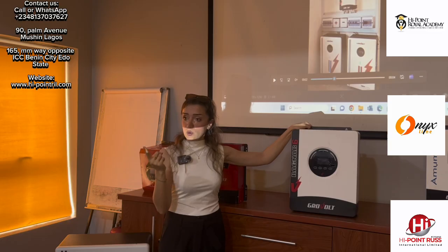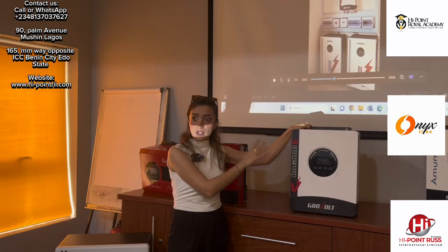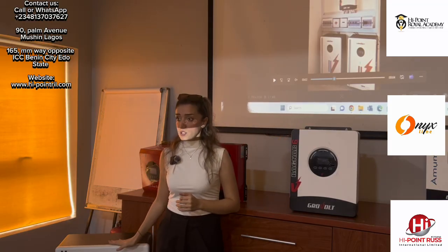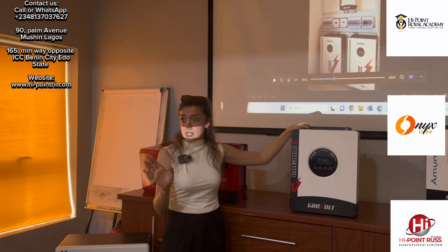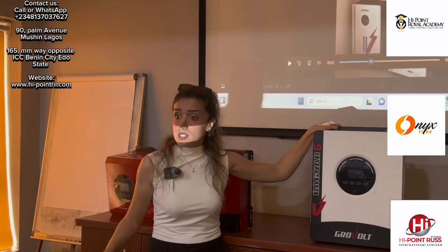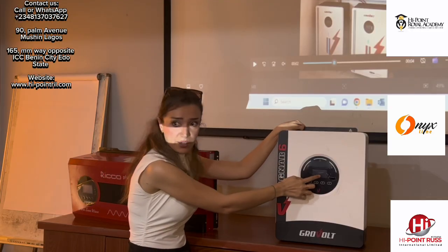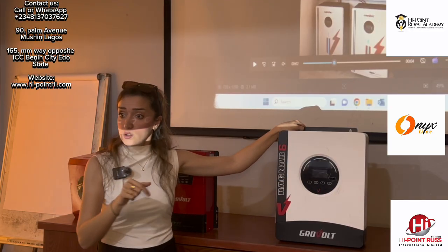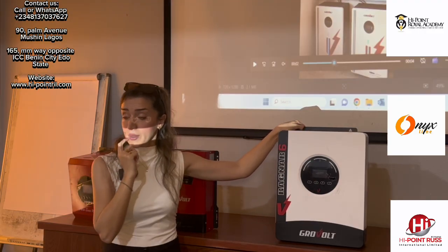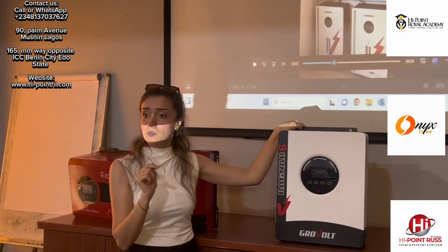If you choose 0, that means it's the default BMS. If the inverter is not communicating or doesn't know about this BMS protocol, put it easily at 0, default BMS. So it will read this lithium battery, but without communication blinking here. If you put 1, you will see the blinking here, BMS, it's working. Then you will go to parallel settings, it's number 20, I think.